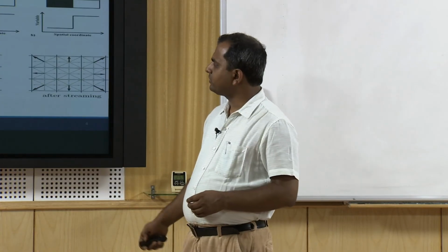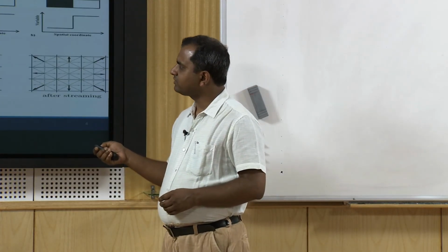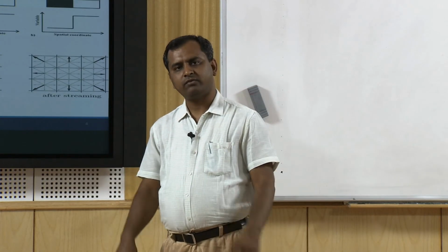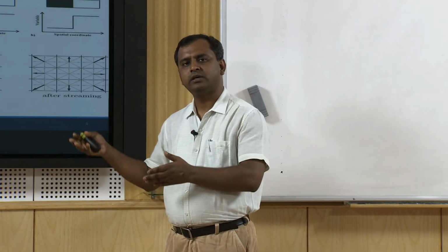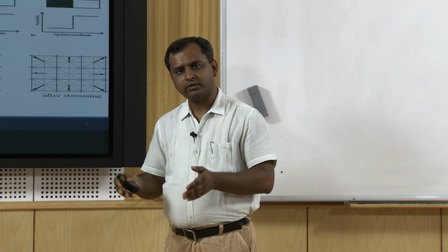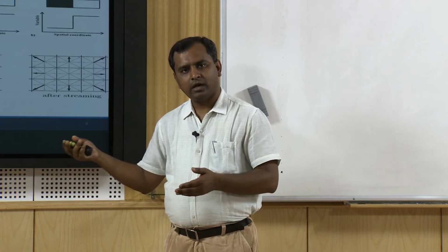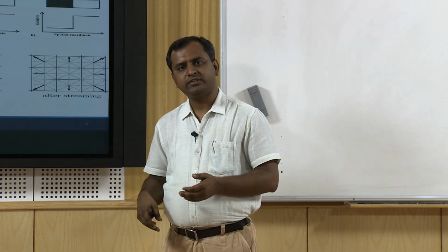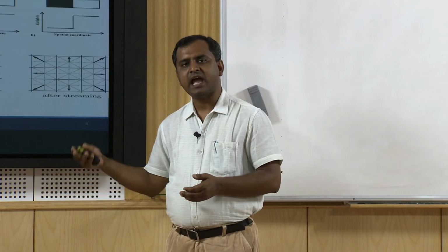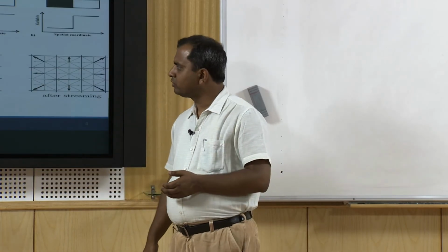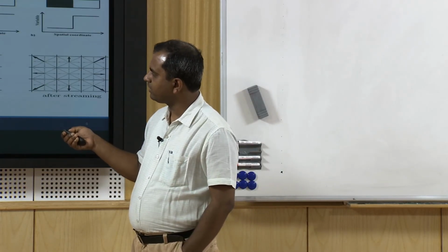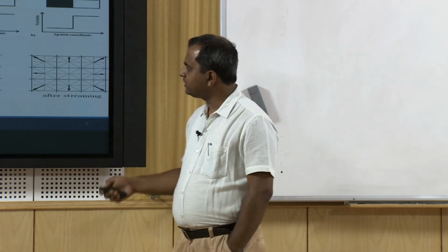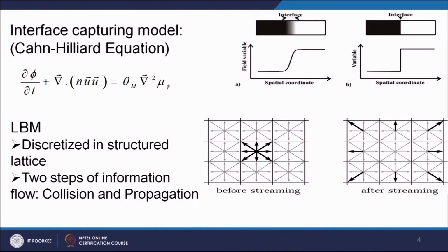Now, Lattice Boltzmann always has a certain mechanism to carry forward the information. That information will be the information for your governing equation parameters, that means rho, phi and n in these equations. Let us say some information is being generated here in the center lattice. This information can flow, depending on the lattice configuration, in particular directions only.